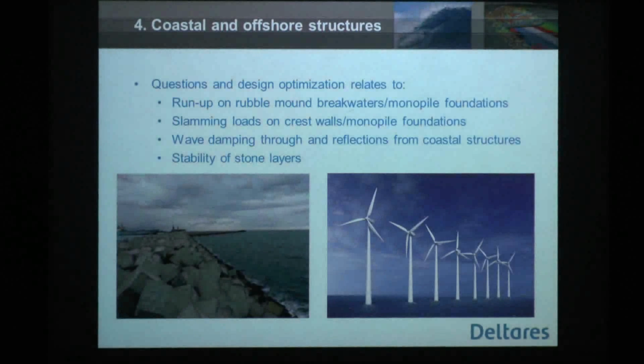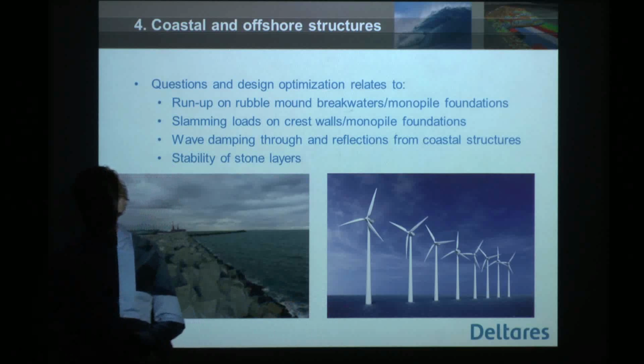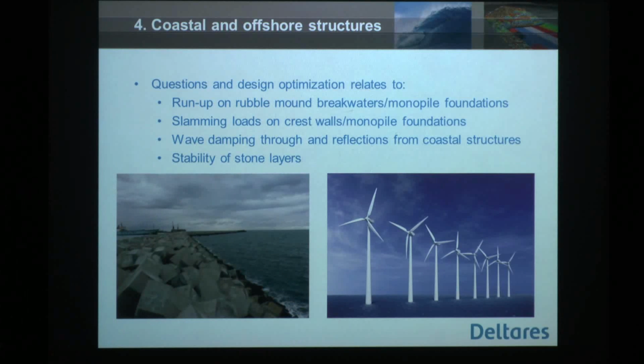So going to what I do more today on the coastal structures and offshore structures, there's quite a few questions being asked in the design process, and these are some of them. There's run-up on rubble mound breakwaters and offshore monopile foundations, and for the foundations it's how far up can we actually put the installation or inspection platform. We need to get there, so we should have it as low as possible, but we don't want it to be torn apart by the waves, so it should also be quite high up.